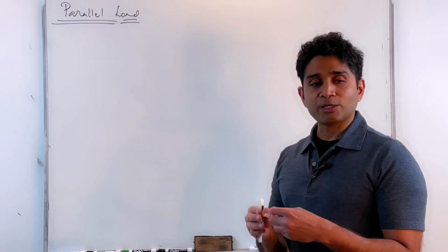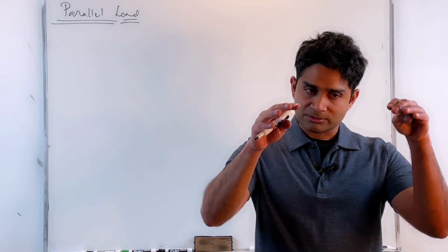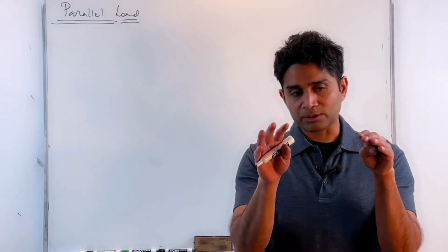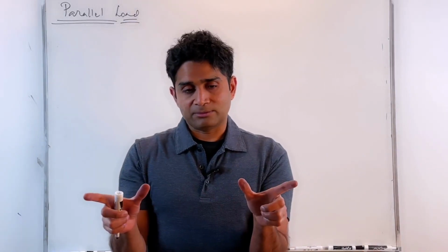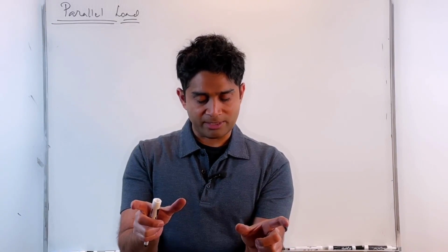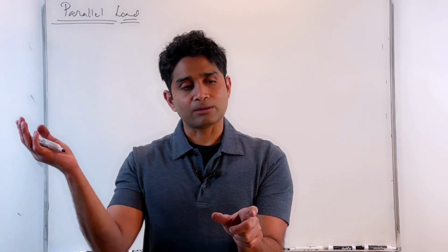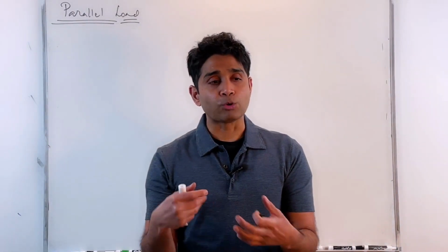Once the load enable signal is enabled, all the data comes in a single clock pulse and gets stored in this register. So n data lines are connected to n flip-flops, and then n-bit data is stored in a single clock pulse. That's why we call that a parallel load operation.